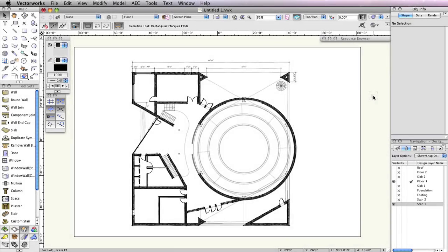There are only 2 stairs in this building, one straight staircase and one platform staircase, which you will create using 2 small straight stairs and a floor object. Since this is only a 2-story building, there are no stairs on the 2nd floor, but you'll need to create a couple of handrails for the balcony area on that floor. Let's begin with a simpler straight stair.